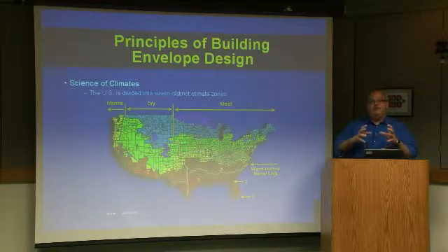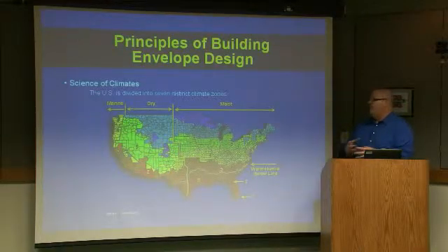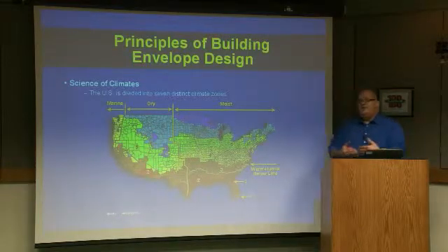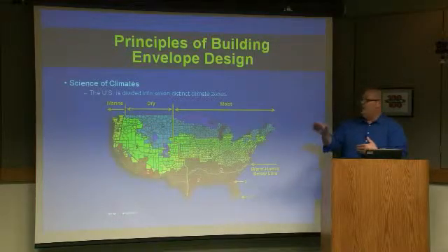The vapor pressure outside is too high year-round. You have very high humidities, very high temperatures, creating very high pressures. Now you've got a layer inside your wall, say your OSB sheathing becomes wet. For vapor to move to the outside, there's got to be a lower pressure outside.